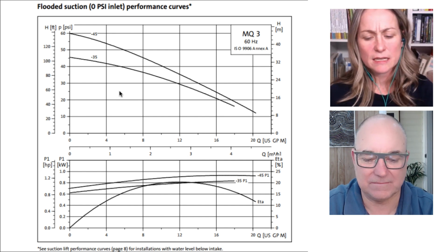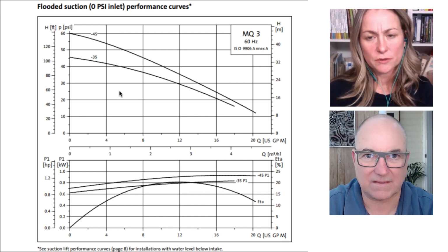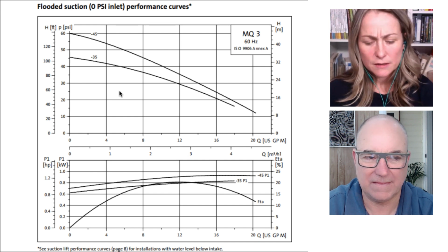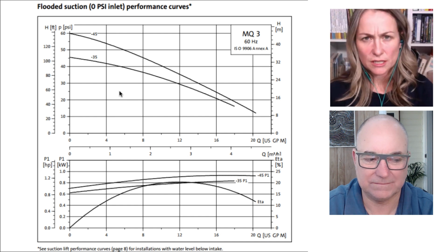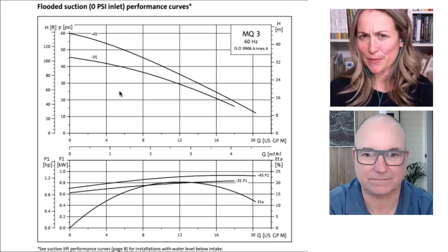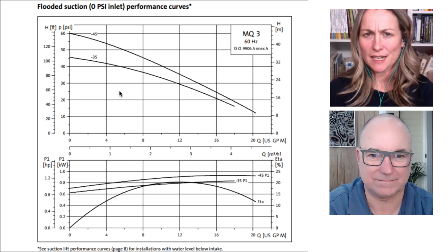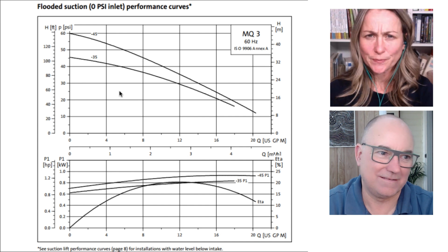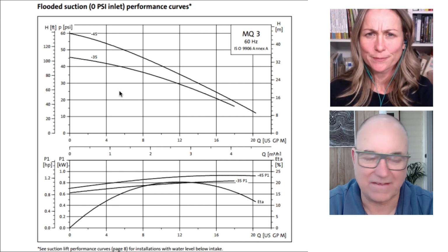But I think you'll get a sense pretty quickly if you start doing a lot of home scale rainwater harvesting designs. You know, if you're a practitioner who's actually doing this professionally, you'll probably find that there's one pump that fits 90% of the applications that you're looking at. And this is what I've found. I've designed thousands of them.